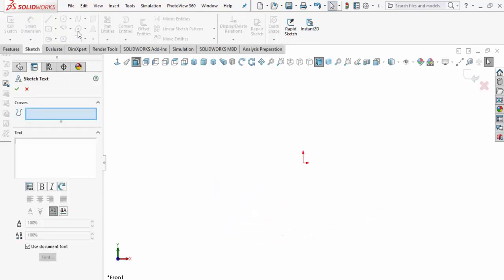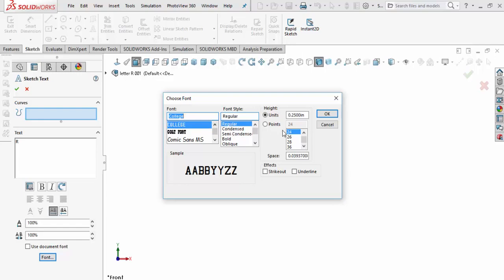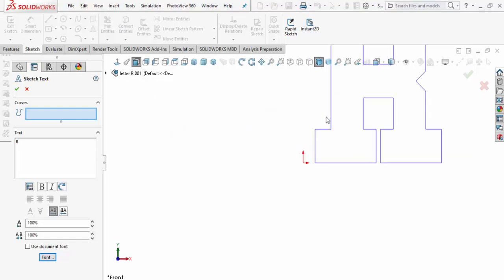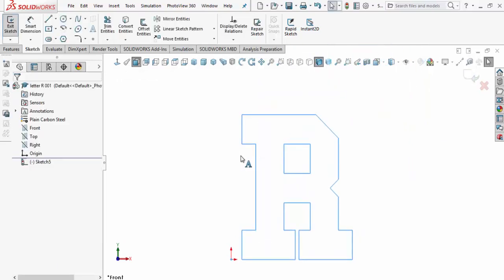Come over here to my letter command, key in the letter R, and I'm going to get rid of the document font and use the TrueType font, which we had selected as college. So I'll type COL, there it is. Select that, give it a size of 65, and make it bold. So we've got that selected, and there's our letter. Let's hit the F command and take a look at it.